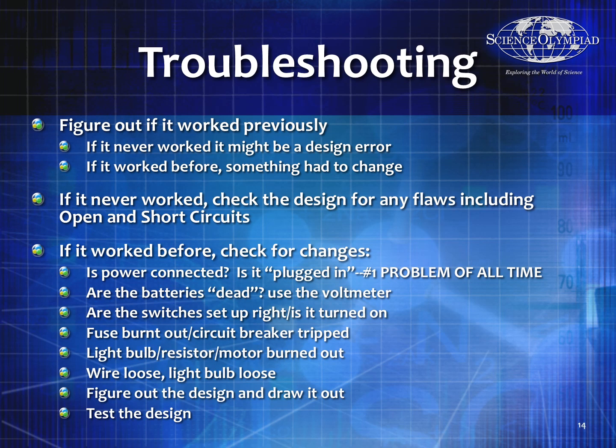But a lot of times on a test, they'll give you a very obvious problem if you just look for the open or short circuit. So if it worked before, you check for changes. Is the power connected? Is it plugged in? Number one problem of all time is that it's not plugged in, or it's plugged into an outlet or a battery that is dead or not working, or the switch is not set up right, so it's not even turned on. The batteries are dead.